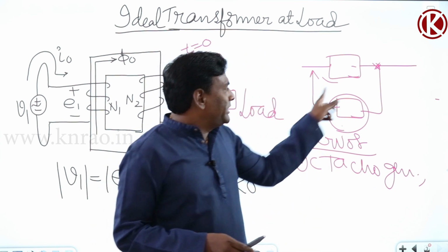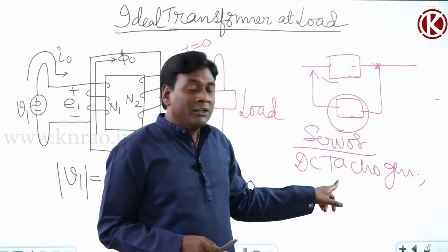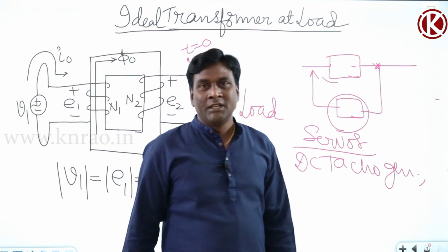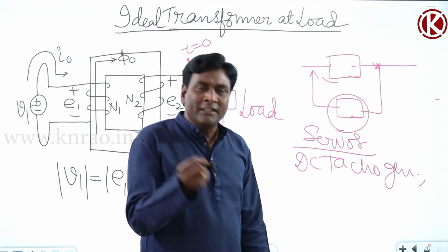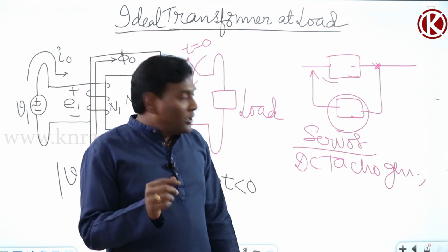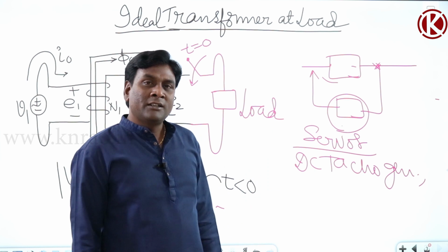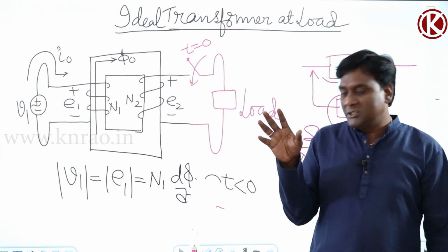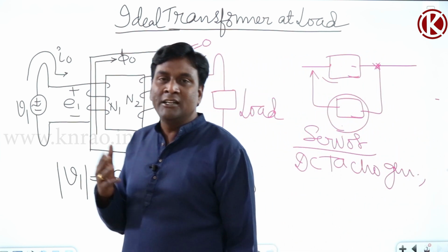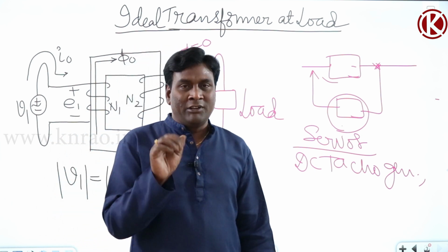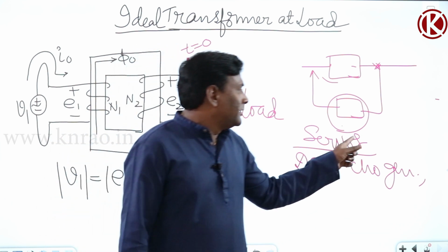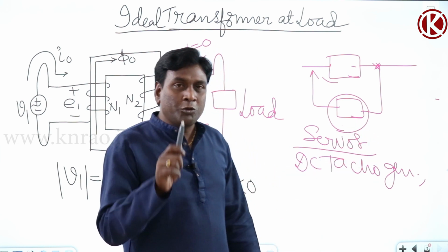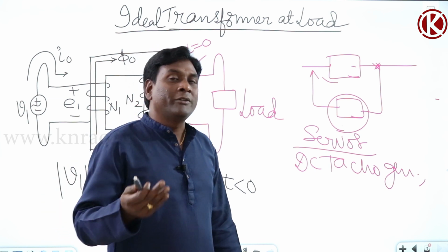So if you think of a servo, a tacho generator, saying the core is laminated to reduce eddy current losses is wrong. Why? Reducing eddy current losses means you should have power handling capacity. Now why do we laminate a DC tacho generator? In future I will prove to you how laminating the core reduces the time constant. Anyway, for servos, whatever you do in the feedback path of the control system should be to reduce time constant and to increase torque by weight ratio.